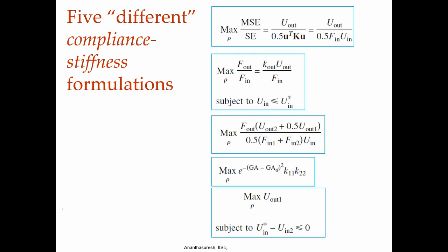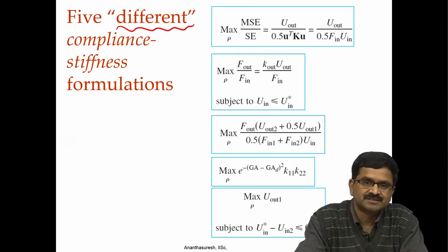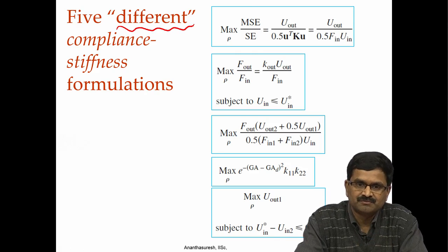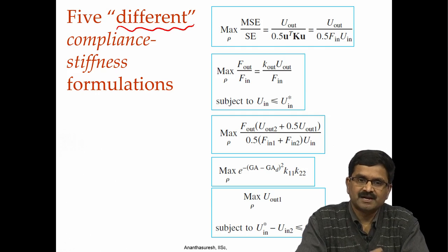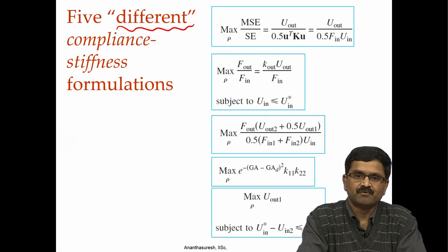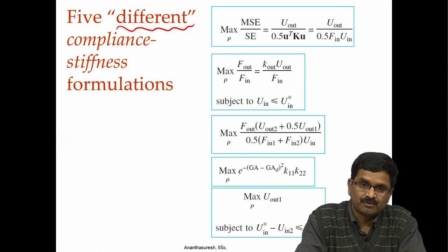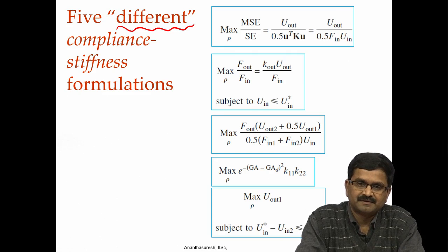So, let us recall that there are these different, so called or seemingly different, formulations, 5 of them we chose, and we showed that they give pretty much similar results in terms of designs, and all of them suffer from this problem of giving point flexures or one node hinges or elastic pairs. There are some narrow portions where most of the rotation takes place, that is a clue to what we are going to talk about, and basically they are like rigid body linkages, right.